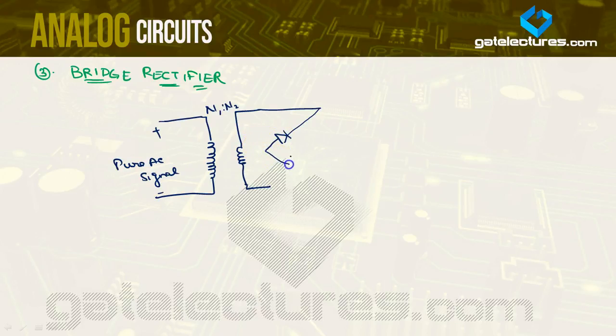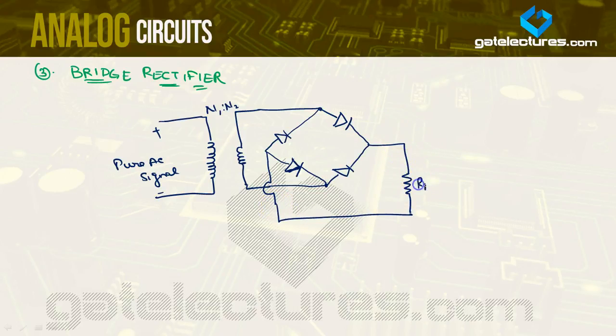It is like this. Let me just draw it so that it is clearer to you. This connection is here, and this connection is like this. This is RL, this is VO, this is VI. This is basically a step down transformer where N1 is greater than N2. This is the output voltage taken, and this is how a bridge rectifier looks. It's again a full wave rectifier, a bridge full wave rectifier.